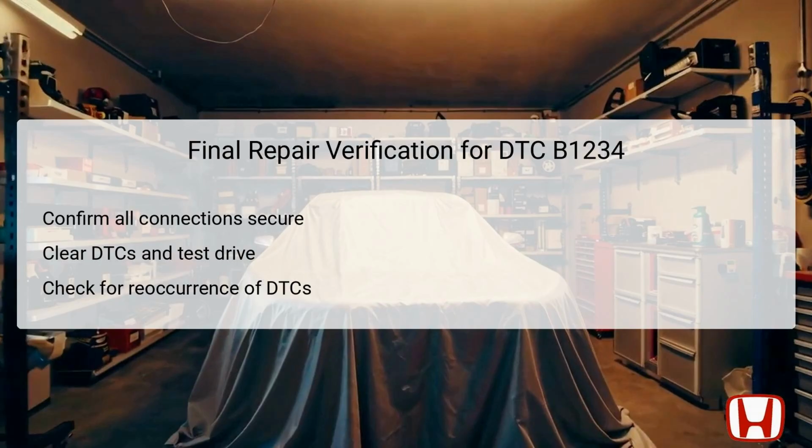Technicians should begin by double-checking that all connectors and wiring are securely fastened and that no loose or exposed wires remain. Following this, the technician will clear any diagnostic trouble codes using the Honda Diagnostic System, HDS, before conducting a test drive to assess the vehicle's climate control functionality.